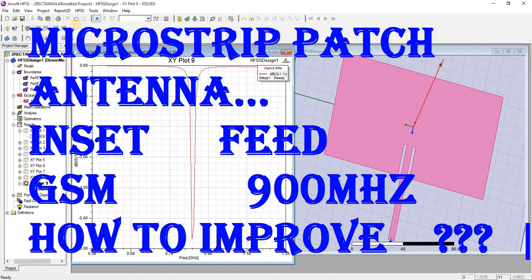Similarly, we will see other parameters that affect the result of the antenna, like what effect changing the substrate height or changing the substrate material will have on the antenna, and similarly what effect will occur by changing the length and width of this patch. And we will also discuss the basic principle of these changes.